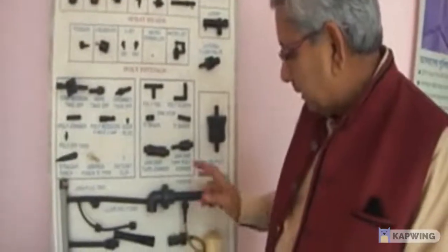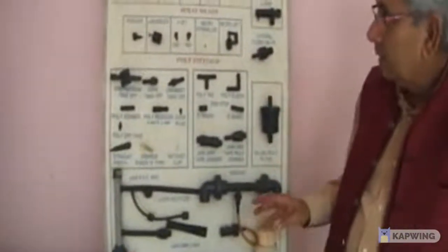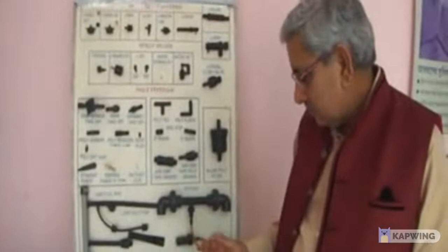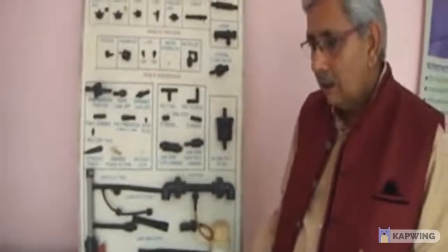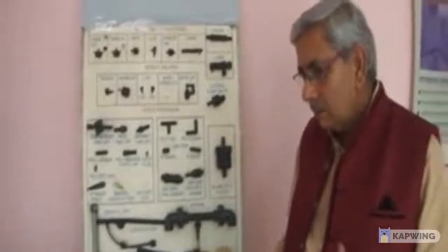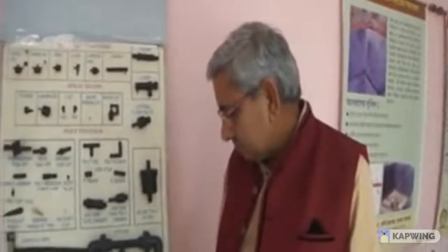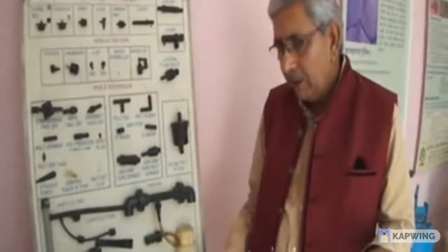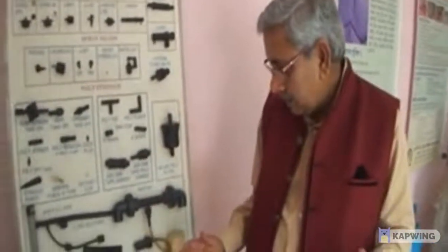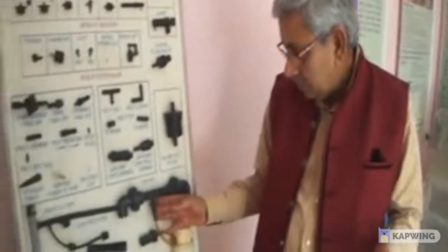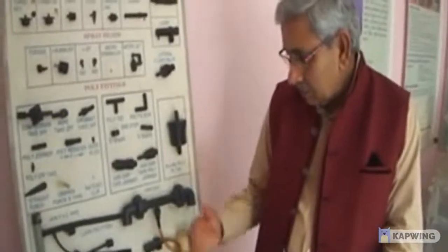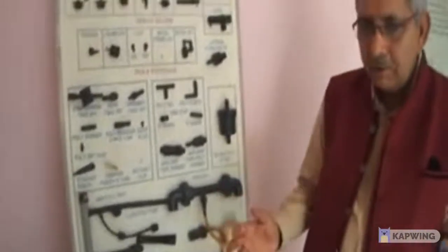And this is an inline filter. Now in the earlier case I was showing you that in a drip system, fertilizer or any other chemical, herbicide or even pesticides can be injected along with the irrigation water. And so injection can be done by using a constant head tank, or by using the Venturi system, or by using an injection pump. Such a provision is there in the drip irrigation system.